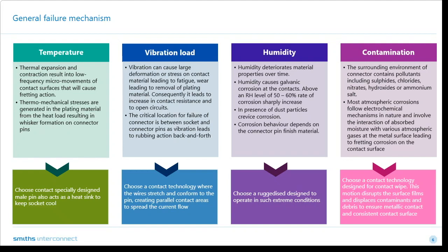And what we have experienced is that what is central in this process to mitigate this risk is the choice of a contact technology, because often the contact, being the heart of the connector, is the one that, if taken care of, in the sense that if the right contact technology is chosen at the beginning, then often you get a superior performing connector for a longer period of time.